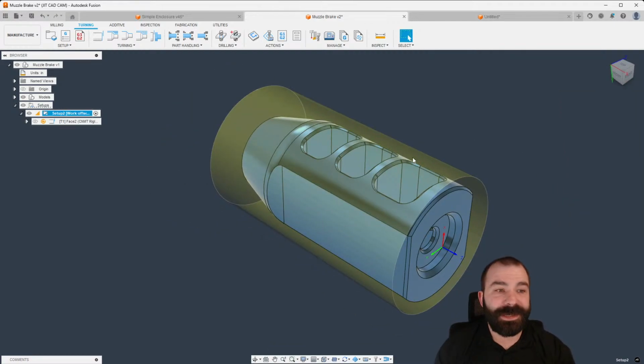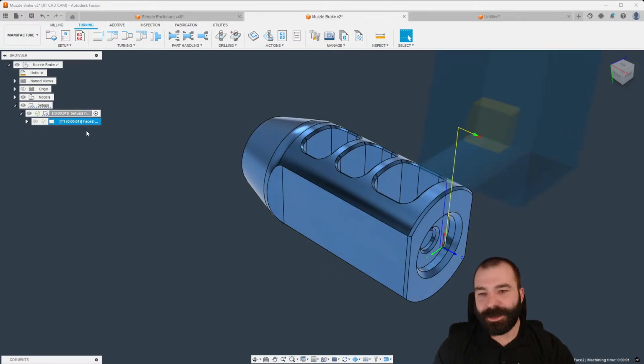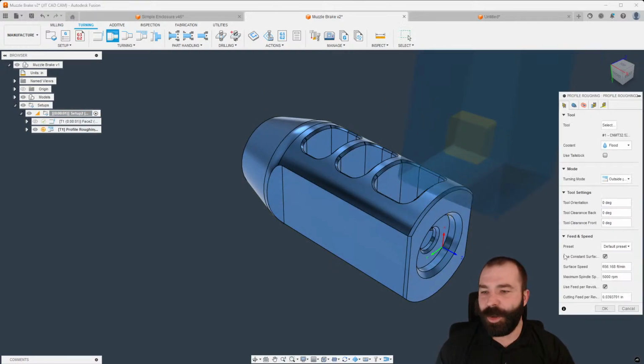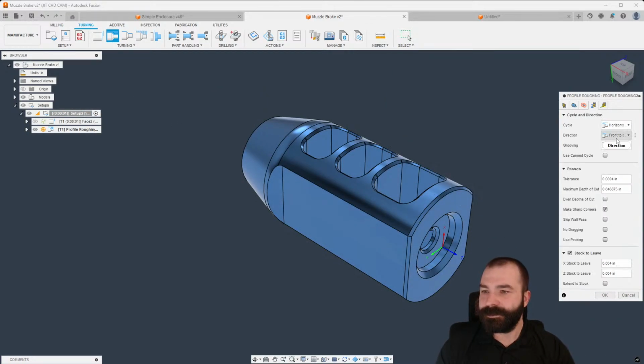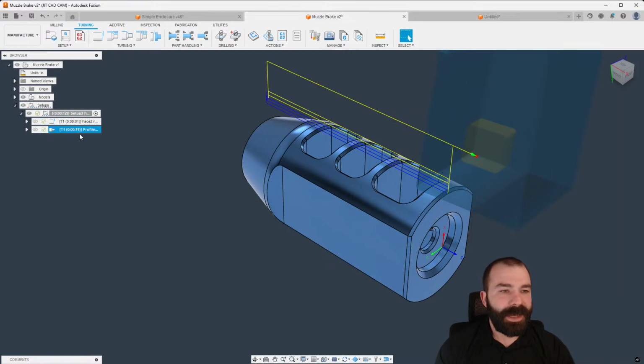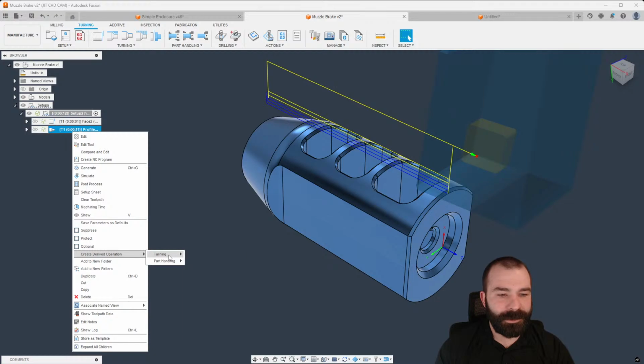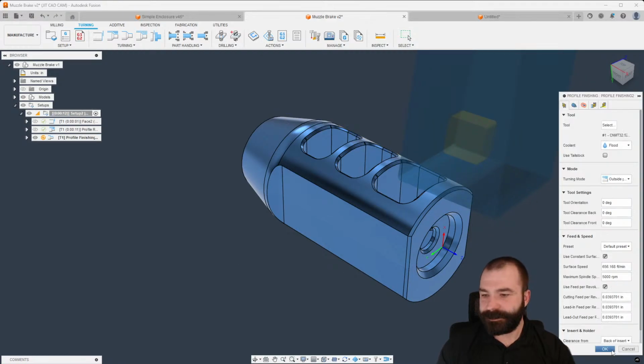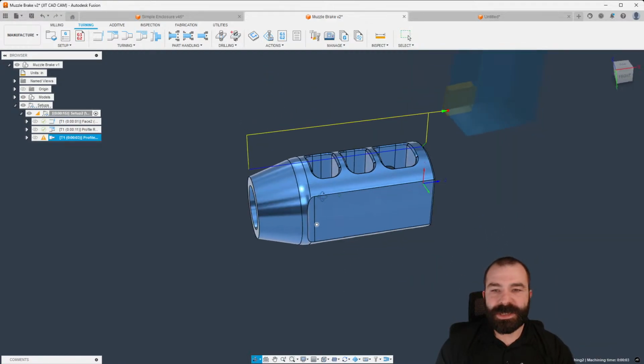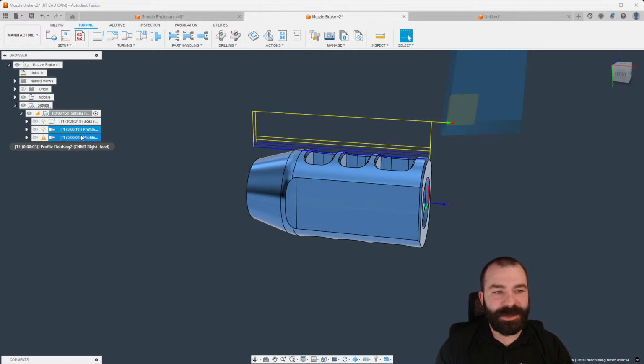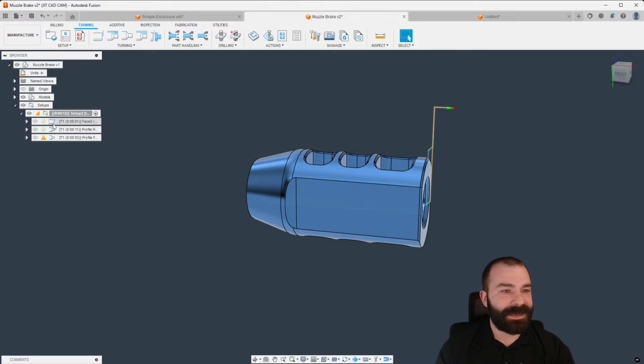We all know that saw doesn't cut straight, right? Here we go. And then let's hit this with an OD rough without axial and radial grooving, of course. And then we can do our finish. There we go. As you can see, I've basically added my toolpaths to my part. I'm going to go ahead and turn on stock, maybe. Play in process stock. Oh, that's right.